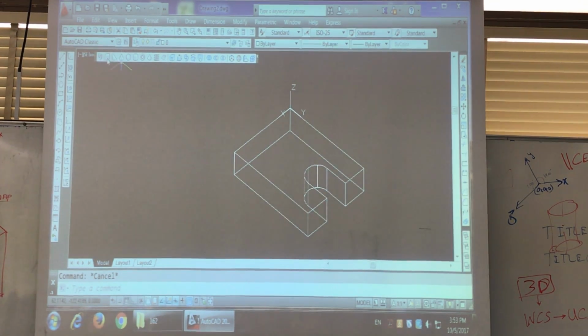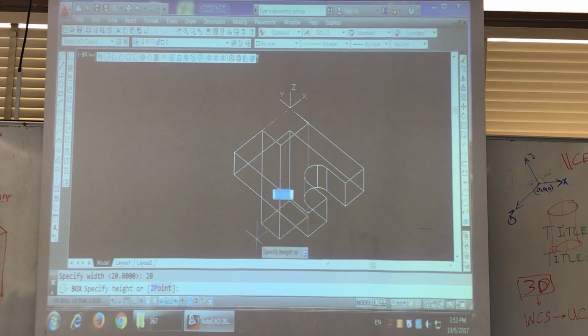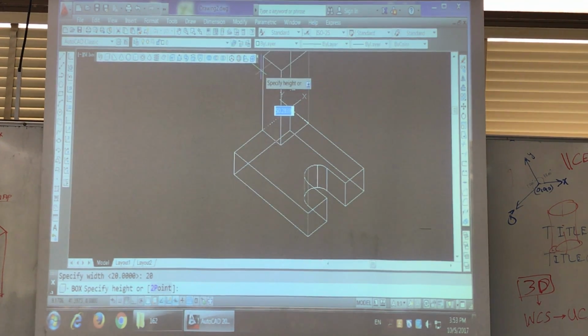How is it 30? It's given there, 30 dimensions. So I will take a cylinder or a box, sorry, and in this direction, cube or length, L, enter. Then it will ask, what is the length? So in this direction, how much is it? 30. Then press enter. Then in this direction, how much? 20. Enter. Then shall I go down? Up. How much? 25. Very good. 25. Enter.